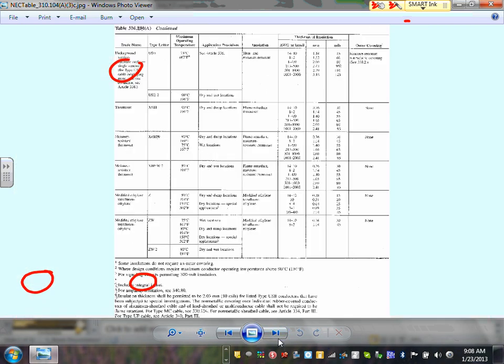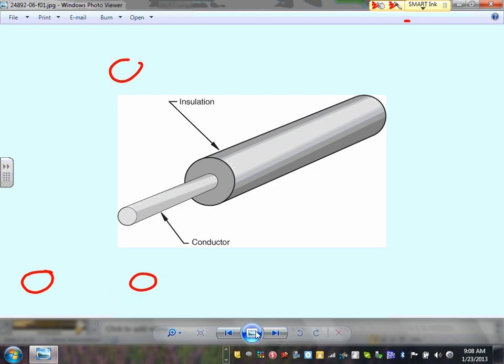Talked about these. That's all I have. Any comments, my friends? Any questions? Please read this chapter. Please do the calculation. The only thing I would like to do out of this chapter, not this week, Jeff, is do voltage drop calculation. Three-phase voltage drop and single-phase voltage drop calculation based on the K and the R. I like the R because the R is always in the code. You don't have to worry about the K if you use the R. That would be part of our calculation. We'll do a voltage drop.